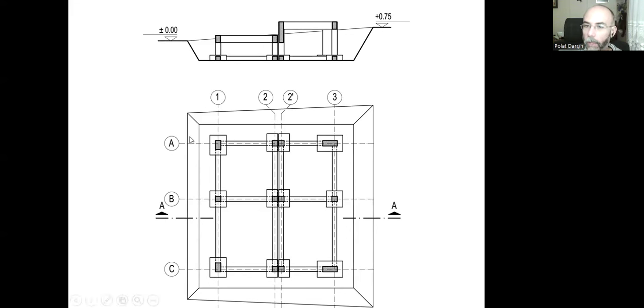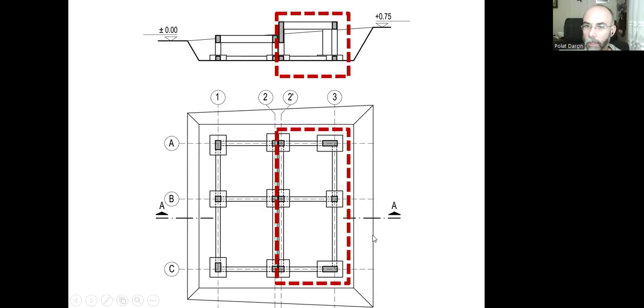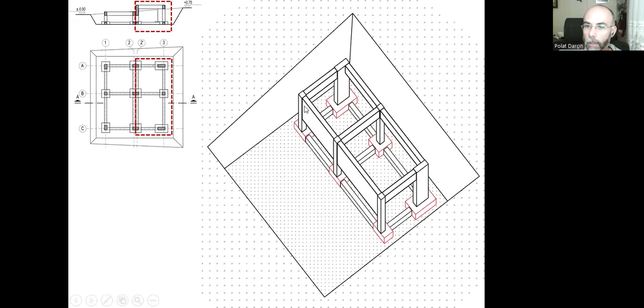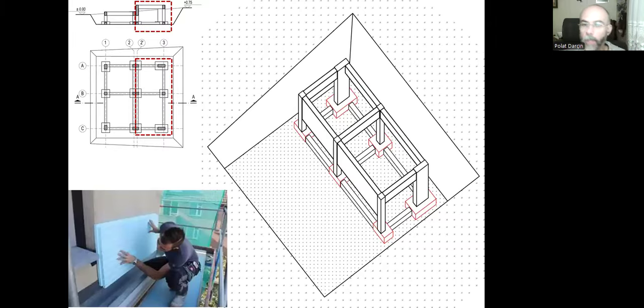And we can create two different foundations. First, we can construct that part of the foundation. As you can see, the footings are half here, and that's a complete foundation. It's finished now, and we can use XPS boards to cover these whole surfaces.